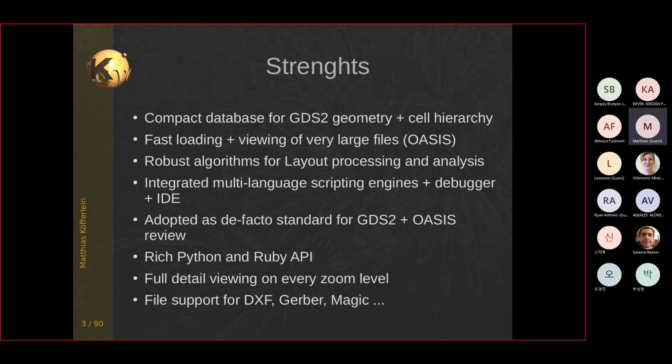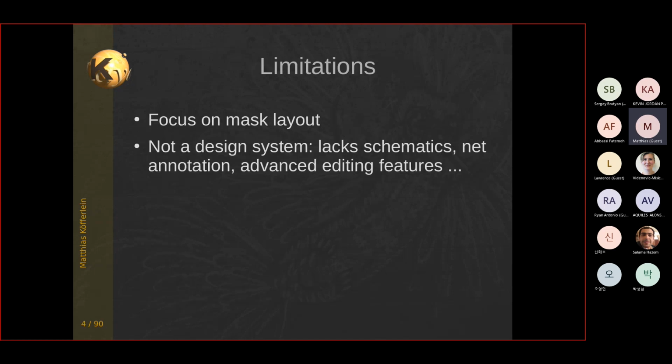And I want to see a specific shape, which is maybe an XOR difference, so the delta between two masks. And I want to see this one, and KLayout doesn't optimize it away. So I have a chance to really see that, even if I'm on the full mask level. And that's something that is very useful for me personally, because you're basically looking for a needle in a haystack. You want to see a specific shape. Well, that's my personal favorite feature, but I don't want to advertise too much here. You will find others who do that.